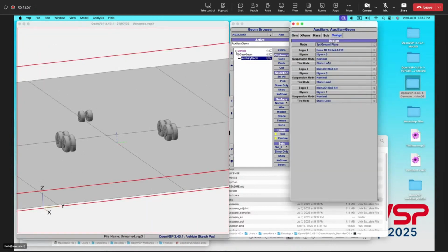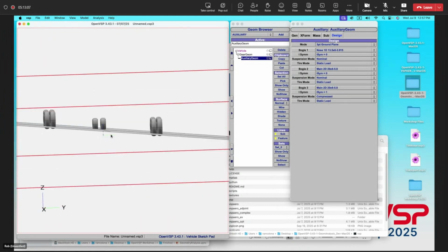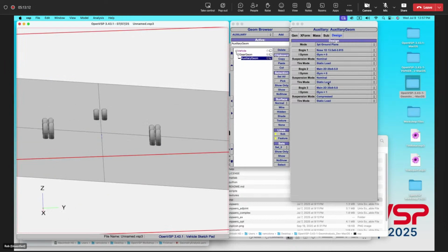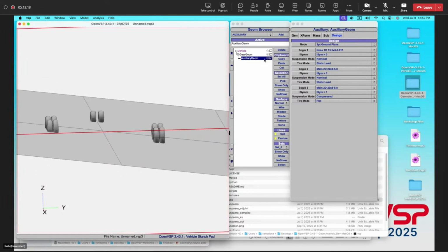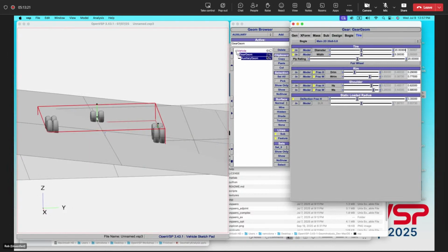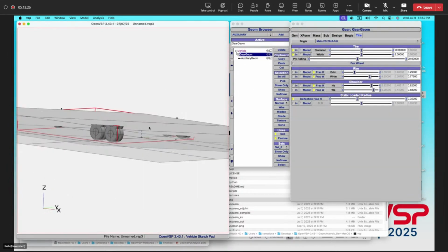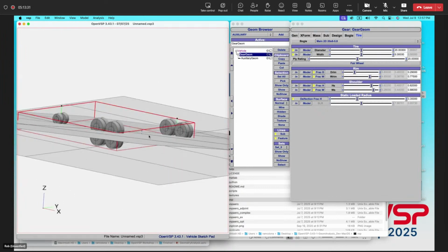And so I can come in and specify the state of any of the gear. Let's take this landing gear and say it is now compressed. Now you can see that it jumped because the left gear was compressed. And we can make the left tire, say, flat, so that means it's going to ride on the rims. That's how you can control what an off nominal gear state looks like. And if I show them both, you can see how that movement is, right? So we have the nominal gear position and then that off nominal. So that's what you do to set up and use all of these.